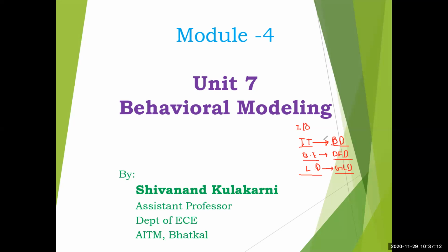Some digital designs and some real-time designs will come here. That's why the combination of data flow description and behavioral description we call the RTL description. In some cases in the behavioral blocks, we may be using the operators of data flow description. For example, when you are writing an if else statement, you'll be using some relational operators. That combination is what we call RTL description. Hope it is clear. So what is behavioral modeling? That we try to elaborate here.